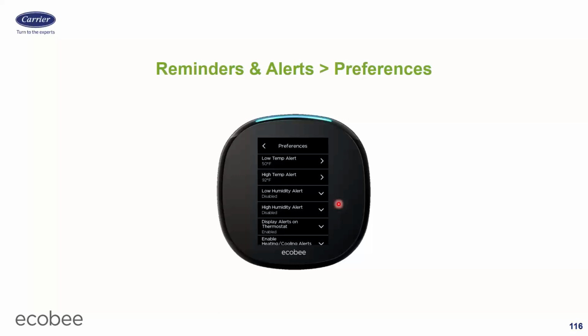The problem is most systems, as you've heard me preach before, are grossly oversized. So getting under 65% is really hard to do. So at that point in time, you're going to have to make a choice. If you're not the one that installed this system and you're just servicing them, or you just installed the thermostat and it's an existing cooling system, I would set it at 65. I would let the alarm go off. And when they call me out on it, I would say, well, you should never have it above 65%.